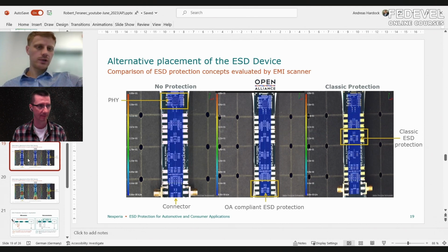And so you can do it several times, going over the whole PCB with your probe, and then you can collect all the data and represent the current. The magnetic field is directly connected to the currents, so you can visualize the surface currents flowing on the PCB. For sure, only on the top layer, because the inner layer is not very visible because of the grounding layer above.